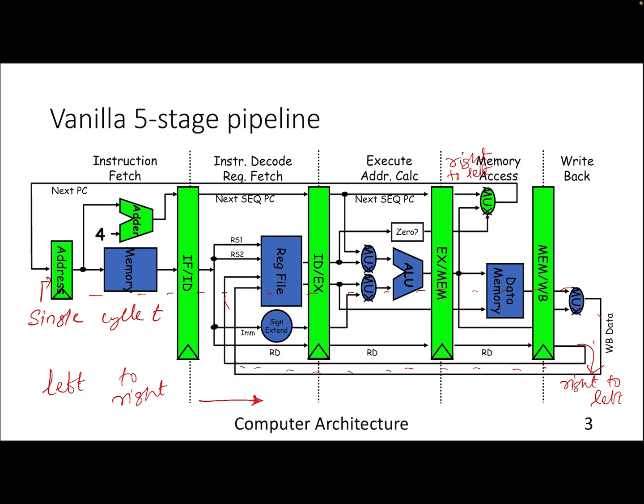So the first stage is instruction fetch, as we are all aware. This is the operation where we are dealing with incrementing the PC. Along with that, the PC is going to the memory, which is called the instruction fetch. The memory is sending the actual instruction. The PC points to an address from which the instruction is there, and memory responds with the instruction.